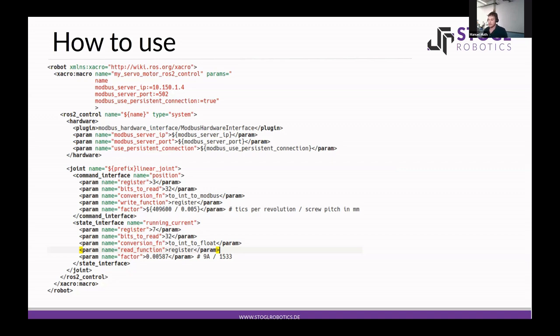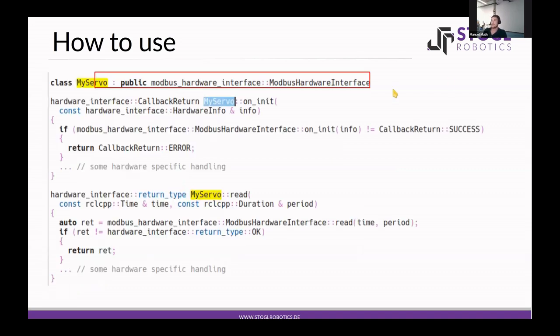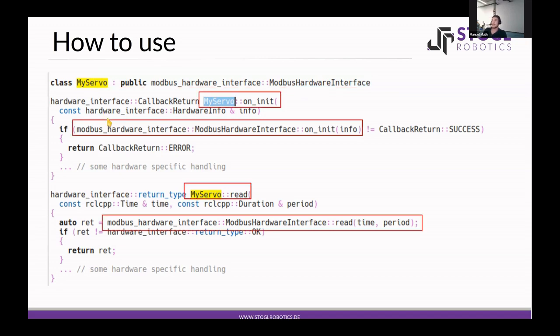And if there's some specific handling needed in your hardware, you can, of course, just inherit from this Modbus hardware interface a class, myservo for example, which needs some specific handling during read or write. One important thing to note is in the onInit method, as well as the read or write method, you always have to call the functions of the base class of the Modbus hardware interface.